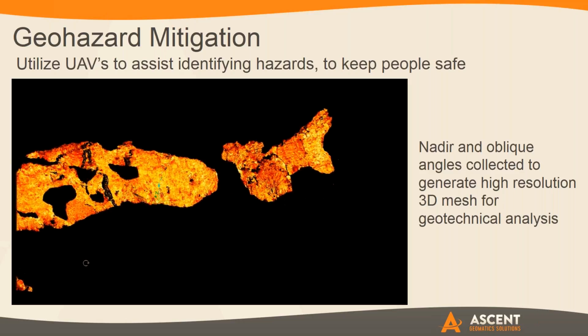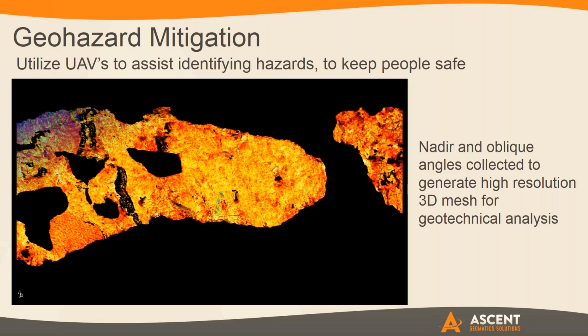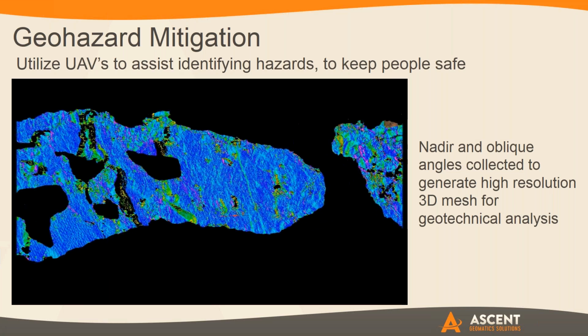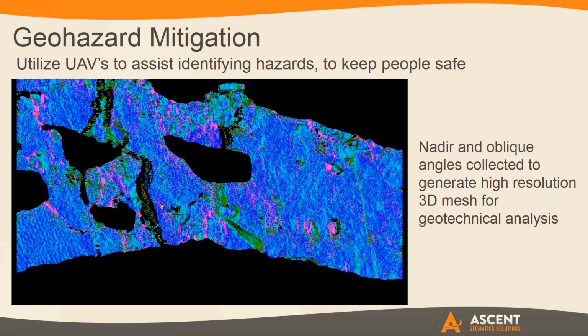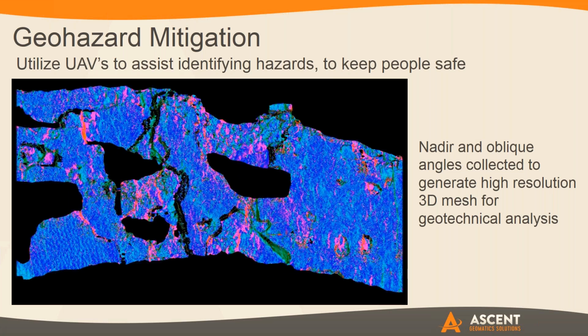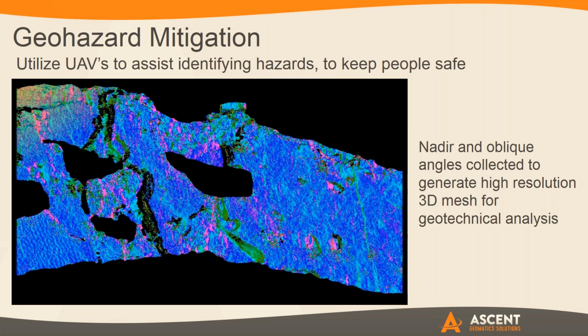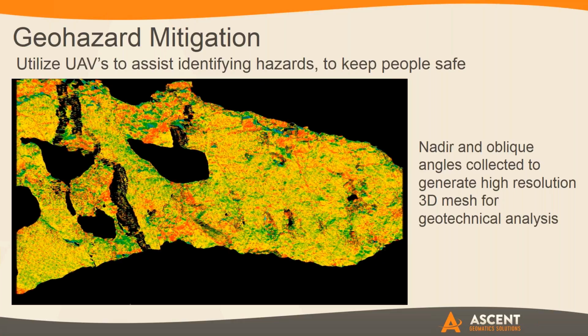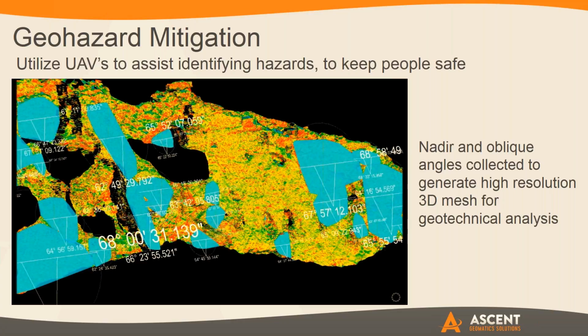And once again, if you're dealing with volumes and quantities and trying to figure out how to develop and mitigate a zone like this, the amount of rock and the amount of material you may have to move becomes money. So how do you better plan at the front end, even before the project starts? Give it a scan, give it a flight, get an idea of what's going on to better understand what you're going to have to do to mitigate this type of process.